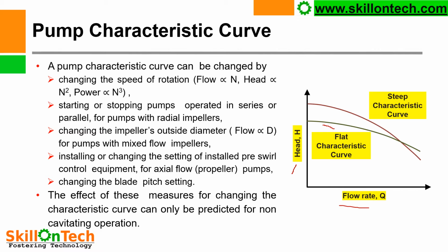Installing or changing the setting of installed pre-swirl control equipment, and for axial flow propeller pumps, changing the blade pitch setting or blade angle, will also change the characteristics curve. The effect of these measures for changing the characteristics curve can only be predicted for non-cavitating operating pumps.